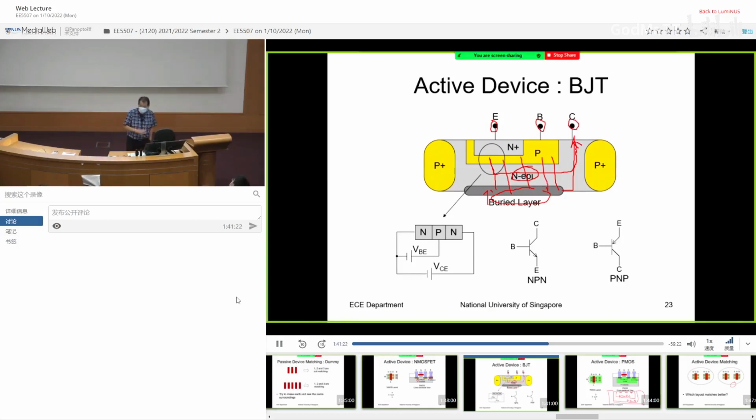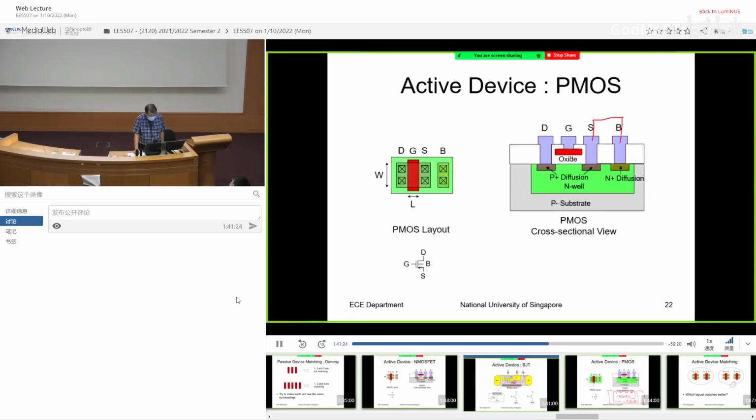Now, we seldom do this. So nowadays, let's say you have a pure CMOS process, you still want a BJT. What can you do? You can make a BJT out of PMOS. So you have this P, okay, and then this is N, and then this is P. So you have a PNP BJT. Can you see that?